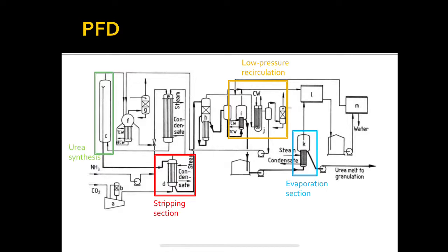The process condensate comes from water evaporation in the evaporation or crystallization section, containing ammonia and urea. Before this process condensate is cleaned, urea is hydrolyzed into ammonia and carbon dioxide. Then it is stripped with steam and returned to the urea synthesis via the recirculation section.